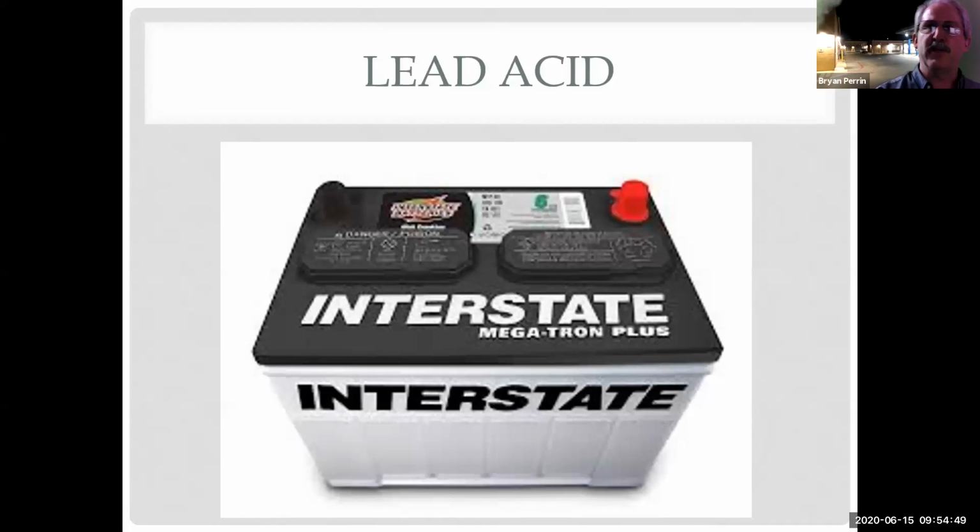The reason why they've been 12 volt batteries up to this point is I didn't want anyone doing decimals any more than necessary. So that's why I made them 12 volt batteries on all of our exercises. In reality, they're 12.6 volt batteries, 2.1 volts per cell, 6 cells in series. Therefore, I have a 12.6 volt battery.